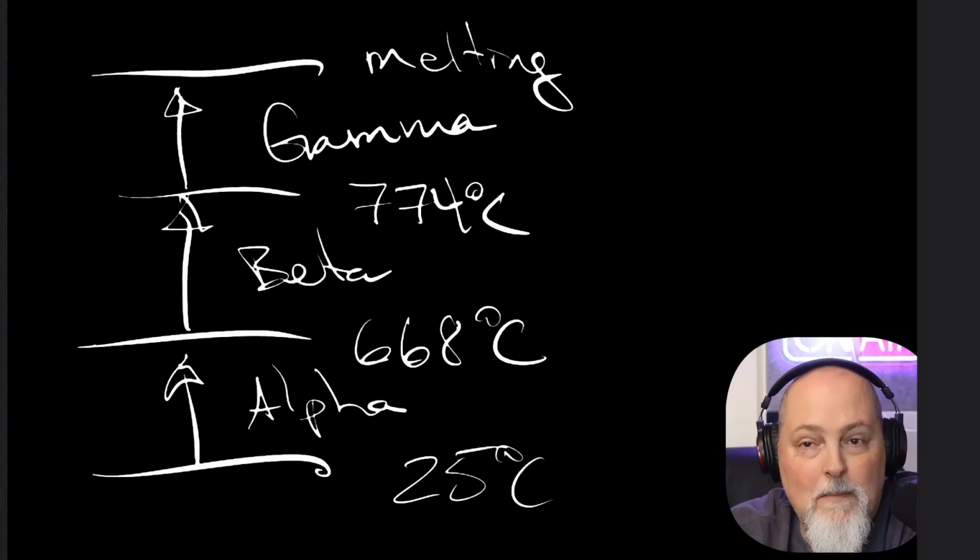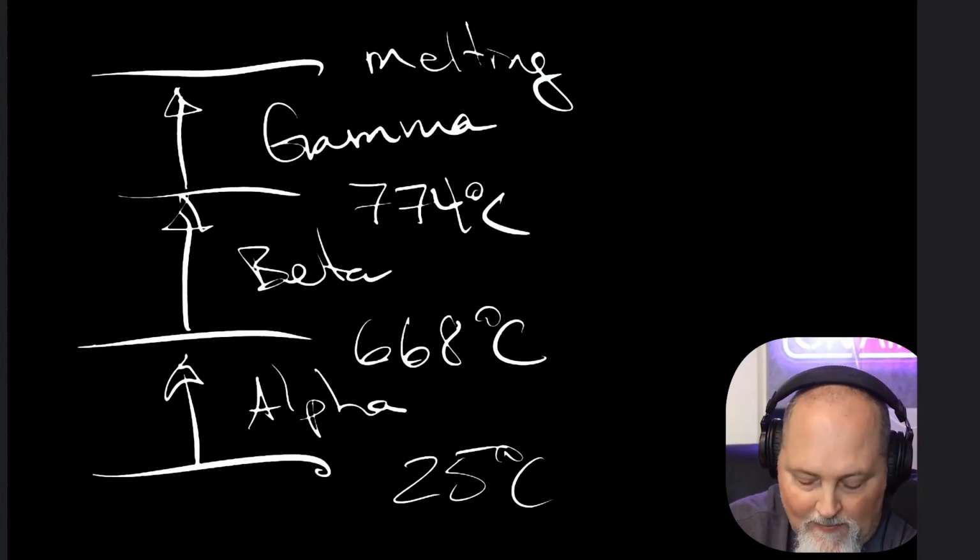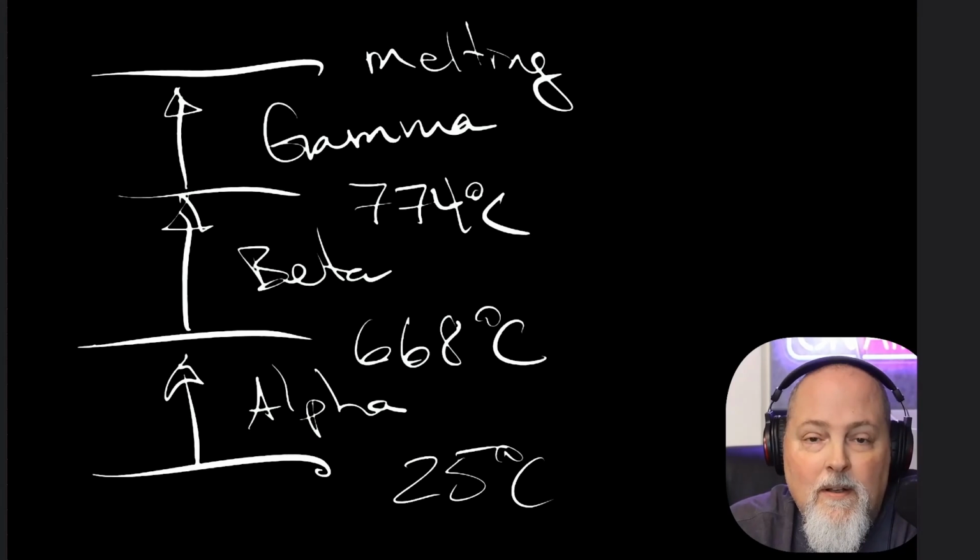So you don't need to memorize all the details of those, but you just need to know which phase causes the main problem. And so the key point for us is that alpha phase prevents pure uranium from being an ideal fuel. If we had a reactor in the alpha phase, it has poor dimensional stability, it has uneven thermal expansion, it warps, it distorts, it cracks, which is why we convert our uranium into uranium dioxide.